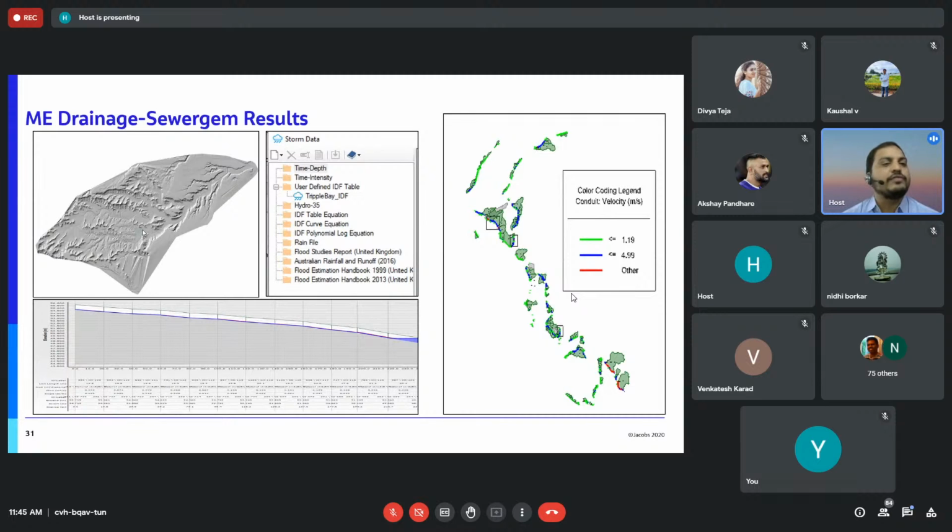So the lidar files will be received in some format, and we can take that format into our QGIS or ArcGIS, and we can delineate the catchments, how much catchment is contributing to that particular stream, and how much flow that stream is going to make, so that at the downstream end we can plan proper culverts, proper size of the culverts, so that flooding gets avoided.